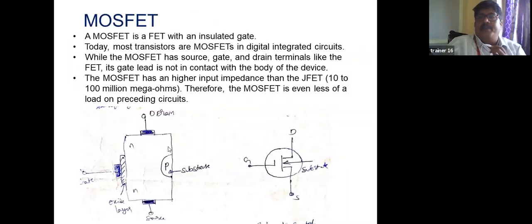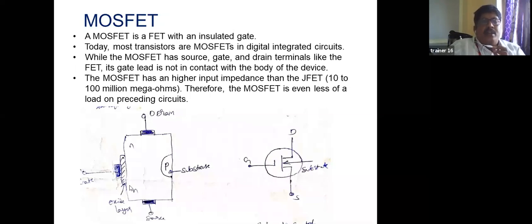If you see this MOSFET, that is metal oxide semiconductor field effect transistor, this is the construction. This is the gate, and the oxide layer is deposited on the N channel MOSFET. On the left side, and on the right side, a P substrate is there, the P type semiconductor. And this is an N type, and this is the gate. In between these two plates, the oxide layer is there, that is the dielectric. The gate is a plate, and the N channel is the other plate.